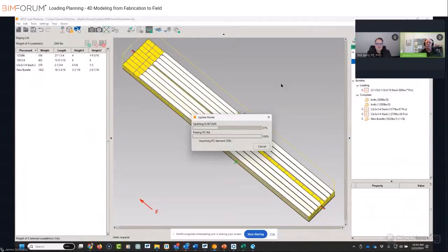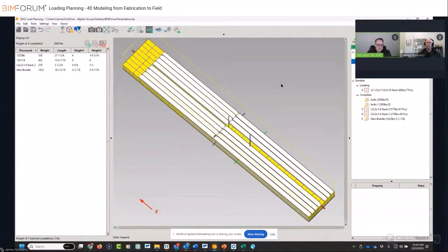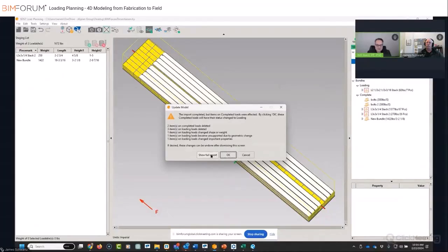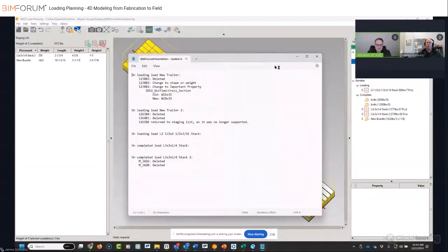Let's say we've got a project, and from an AISC background, we know that field cut beam penetrations are a lot more expensive than shop fabricated openings. Say we're cutting web openings in beams to pass plumbing through, or roof drains, or ductwork.